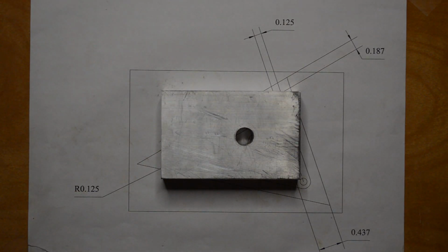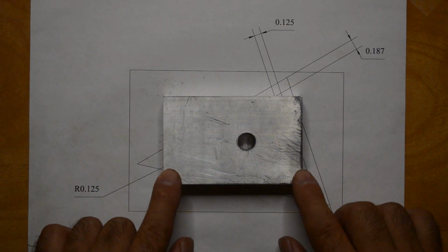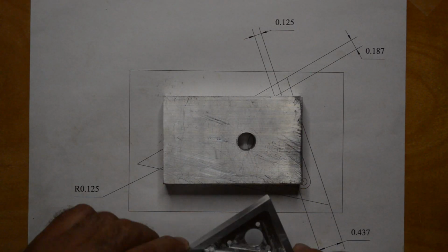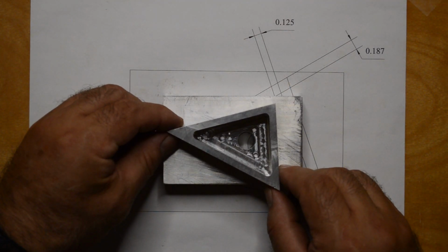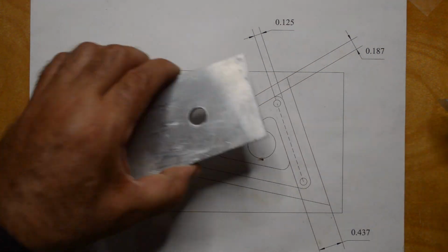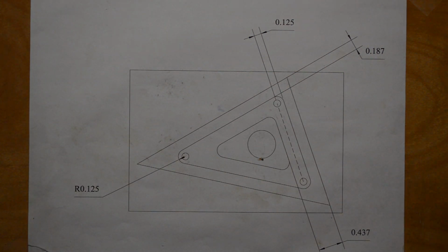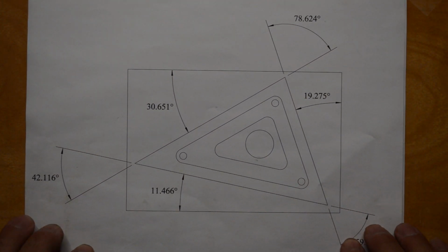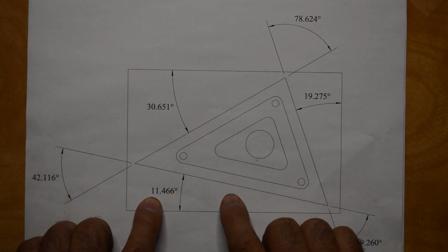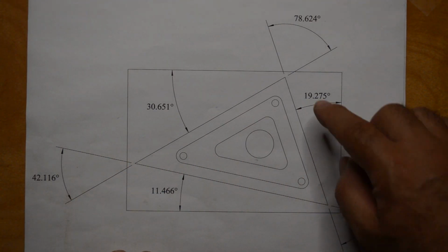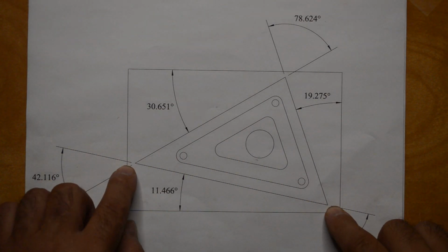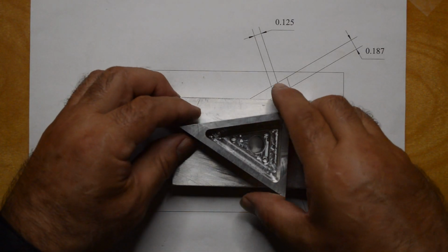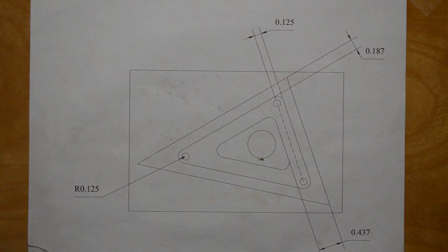And one thing that's kind of funny about this job is that I was committed to the size of the rough stock in this hole location, and I wasn't certain that the part was going to fit perfectly within the rough stock envelope. And so what I did was I went back to the CAD model and I just rotated the geometry this arbitrary angle, right, so that the part would fit comfortably with margins in the rough stock envelope. Okay, so that's why the geometry is rotated on that funny angle.